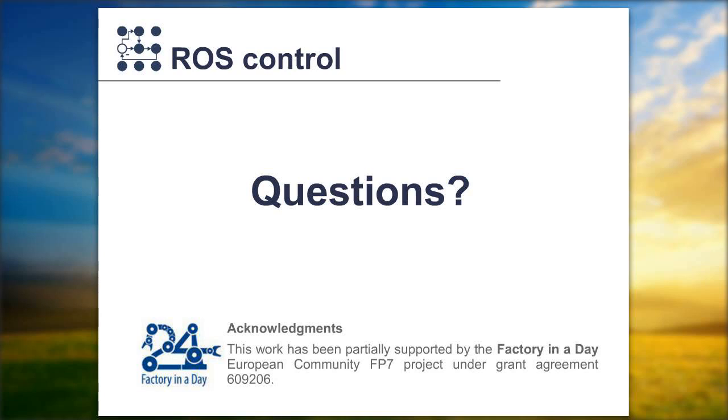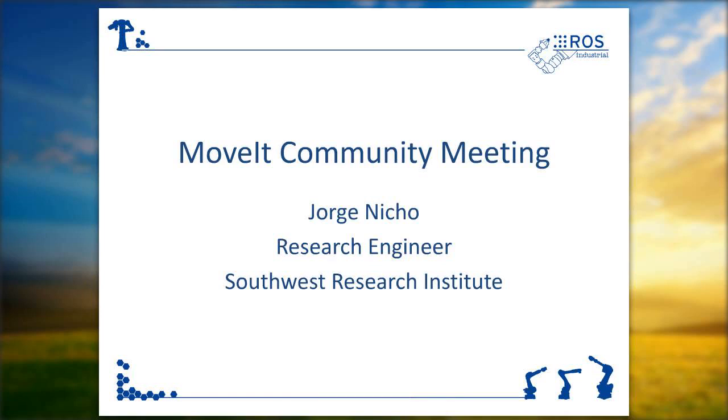And the other question was, are there any Cartesian space controllers in ROS-Control? Yes. I would say that in the official ROS controllers repository, there are none. But I know that there is at least one implementation for Cartesian control of a single end effector that I've seen in use. And also we have a proprietary implementation of whole body control that you can use with multiple end effectors and subject to prioritization, and it's quite complete, but it's also proprietary.